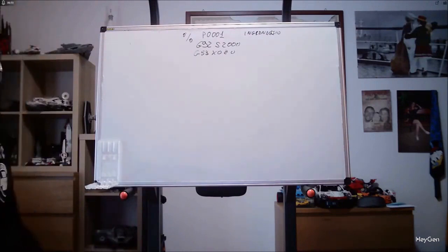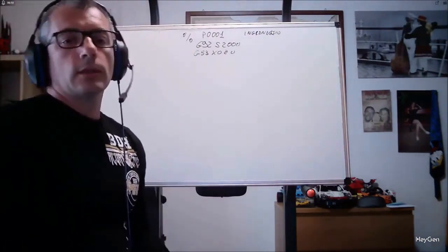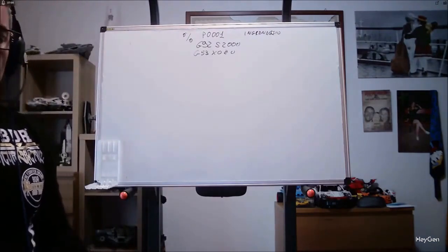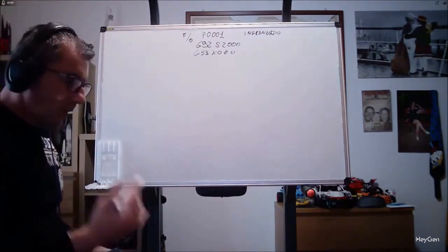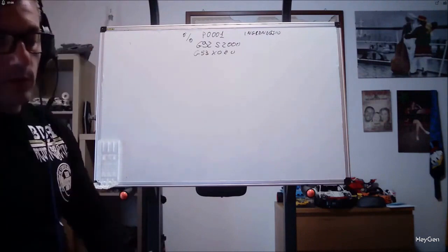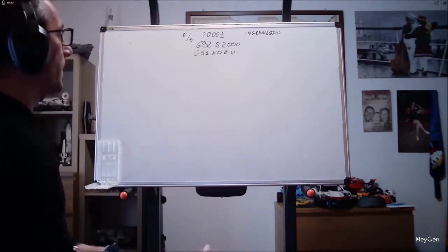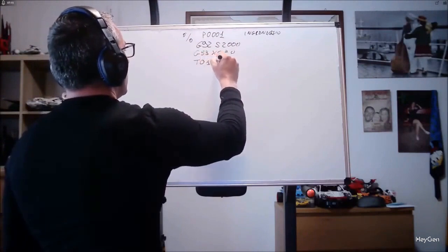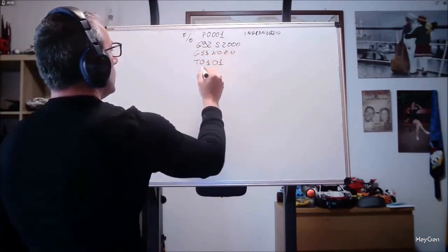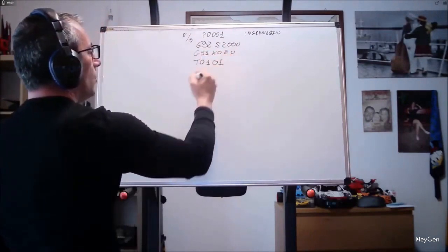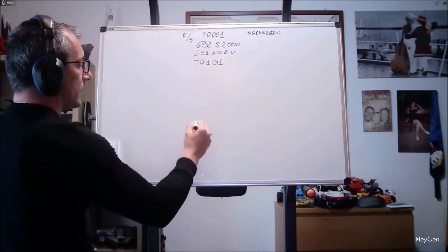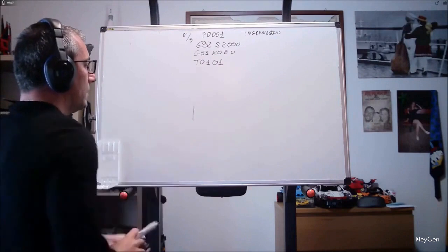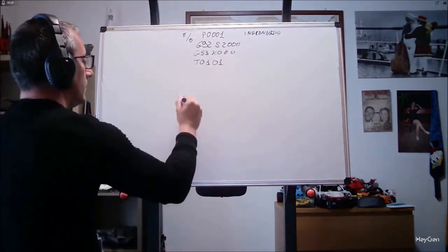After that, we need to start thinking about calling the tool we will work with at the beginning of our piece. So here we have a bit of variation. Normally, when we talk about Fanuc, we write T0101, where the digits stand for the turret position number, because you know that a turret, let's make it octagonal to keep it brief.